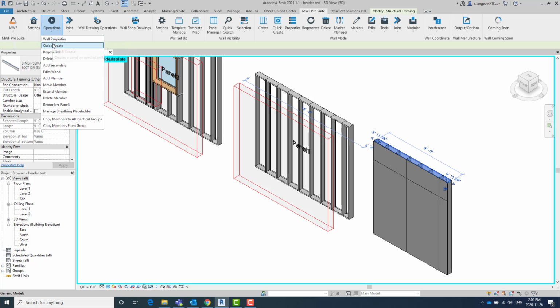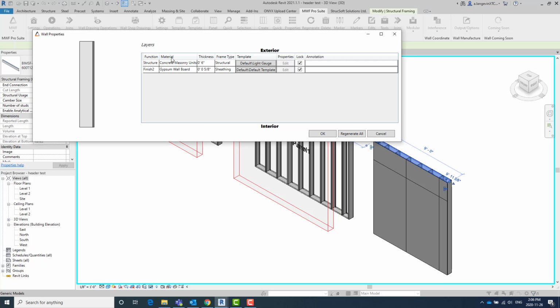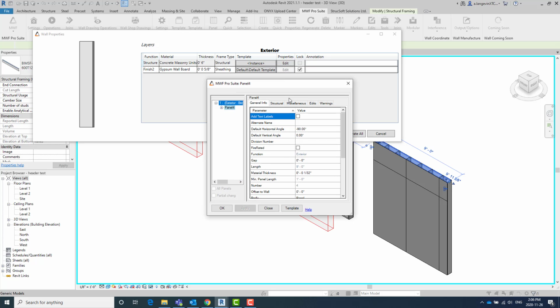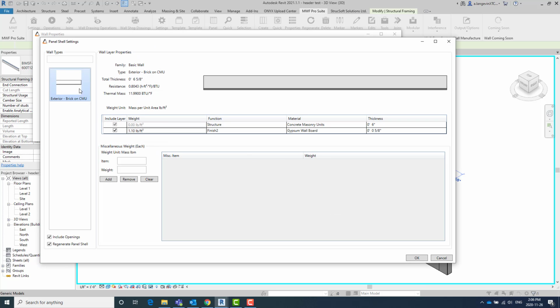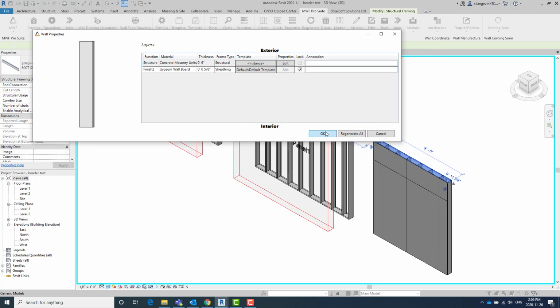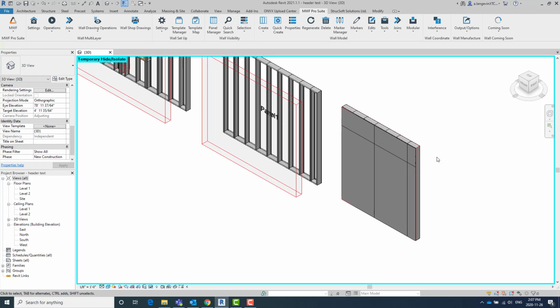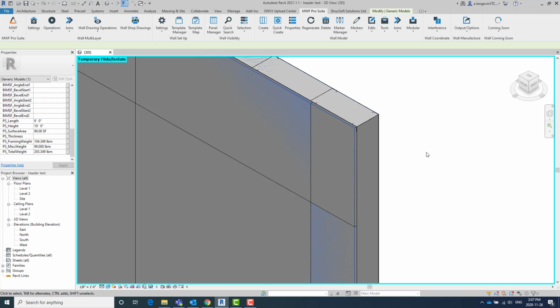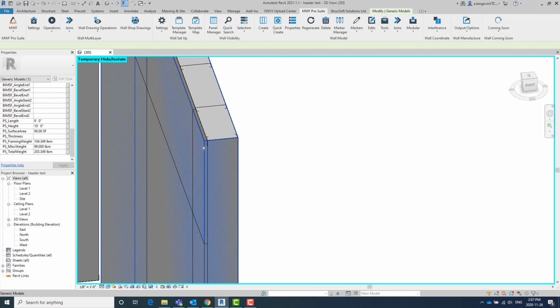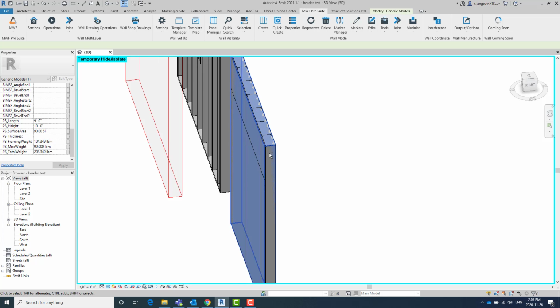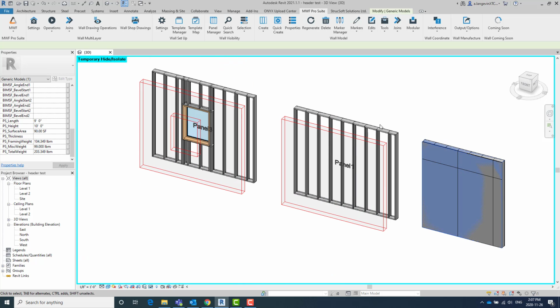I go to operations and I go to the wall's properties. It's using, just unlock. I can go to edit. And under panel shell, this was the wall that I was just showing you before. Then we can go in and we'll see that the shell is a little bit thicker because of the extra members. All right, so this is very useful